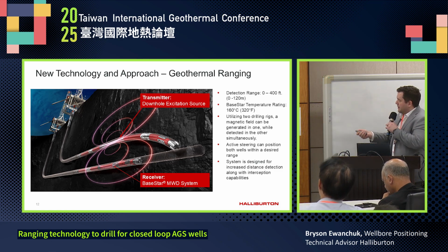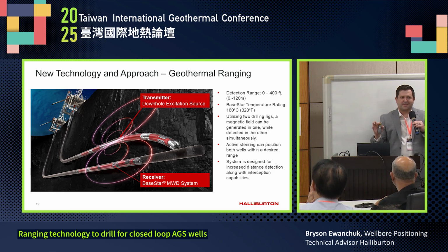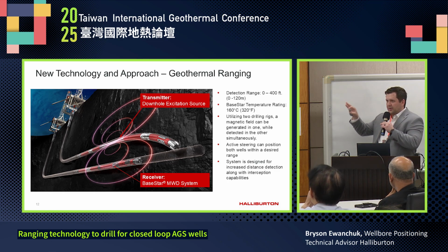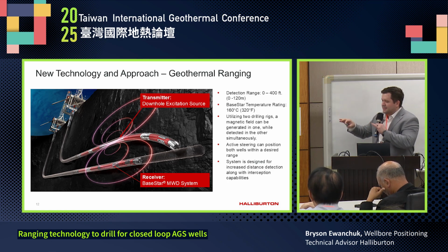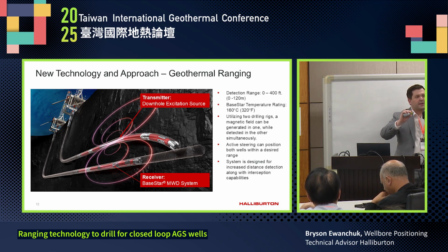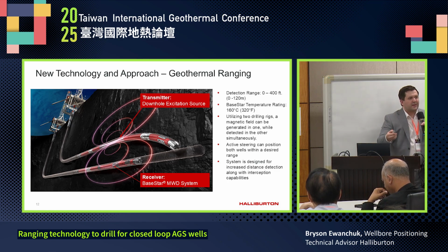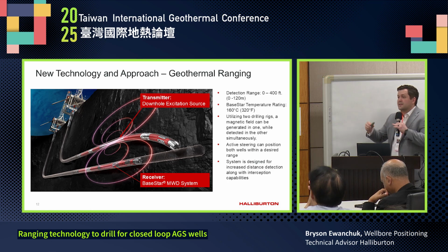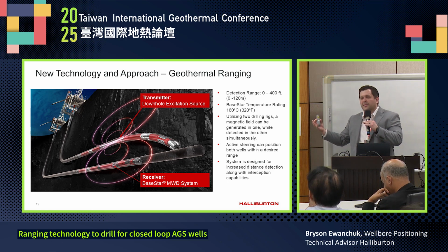I then want to highlight here the temperature rating, 160 Celsius. Everyone's eyebrows are probably going up and saying, oh, that's low, that doesn't work. This being said, this would be the lowest limiting factor of the system, but we don't run it by itself. This system is run with insulated drill pipe. It's run with mud coolers, systems like that, which actually can keep it alive. So though it seems low, it's a number we're trying to improve. It's actually not a problem because we just need a system around it that's in place for it.